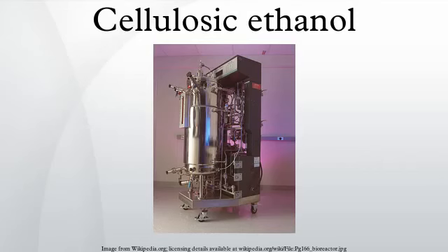The first attempt at commercializing a process for ethanol from wood was done in Germany in 1898. It involved the use of dilute acid to hydrolyze the cellulose to glucose, and was able to produce 7.6 liters of ethanol per 100 kg of wood waste. The Germans soon developed an industrial process optimized for yields of around 50 US gallons per ton of biomass.